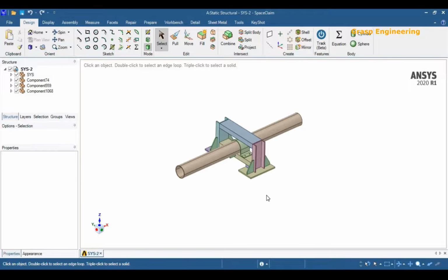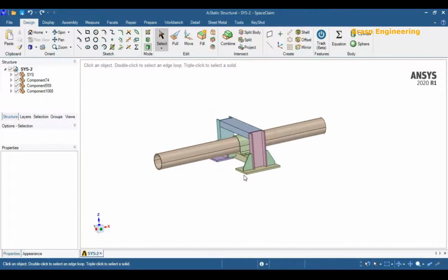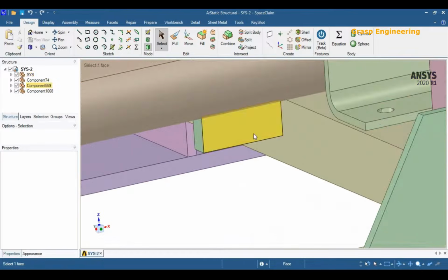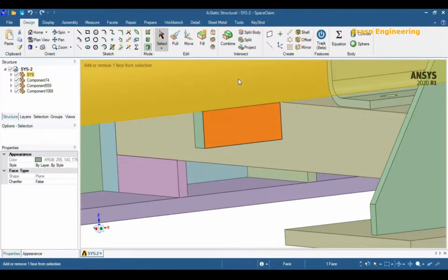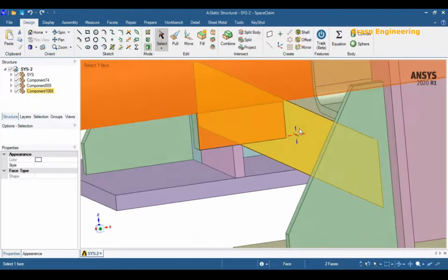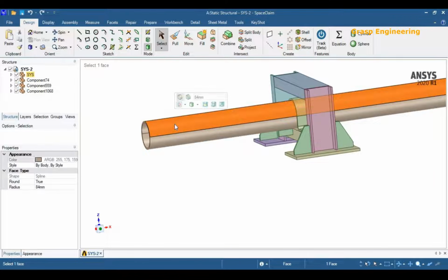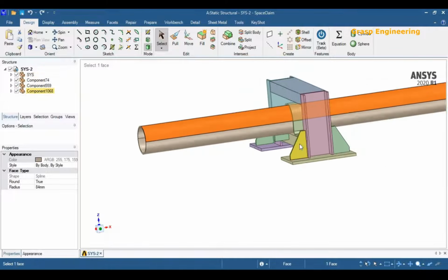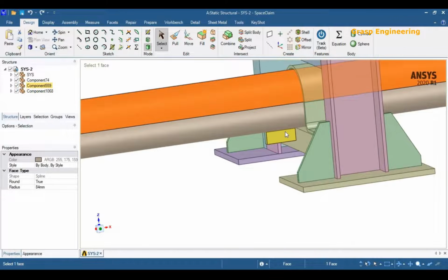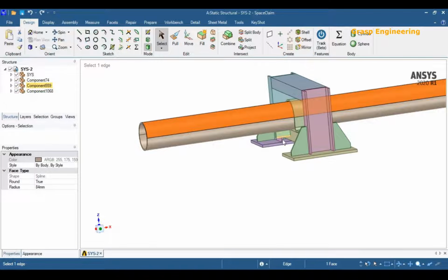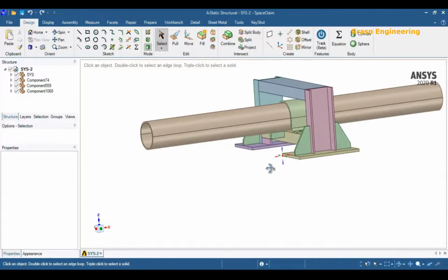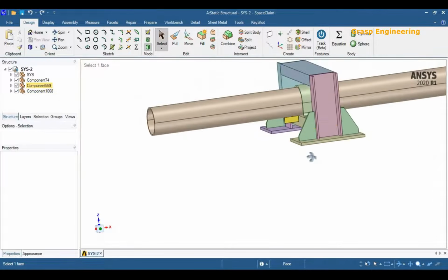So in order to avoid larger thermal expansion, you can provide stoppers like this, which are welded to this pipe, and there is some gap between these two. Suppose due to the temperature loading condition, or due to external loads, this pipe may move into this clamp. So you can put this stopper if you want only a certain amount of displacement. That is the use of these stoppers.